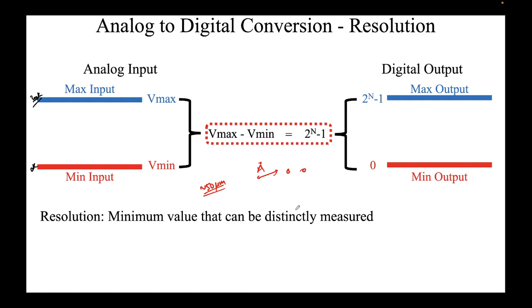In the example that we are talking about, this means a 1 bit change. So let's say the value here was 0, 1, 1, 0, and so on. So these are some bits, right? So 0, 1, 1, 0 was the value. Now the next value can only be 0, 1, 1, 1. Only 1 bit change, only 1 jump. Then only are we able to measure. So this is called resolution. Only when 1 bit changes will we be able to capture the change in the input.